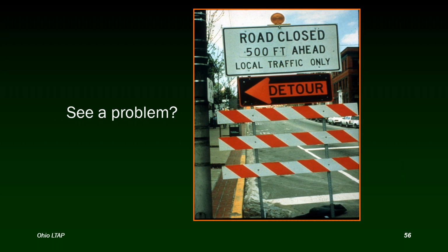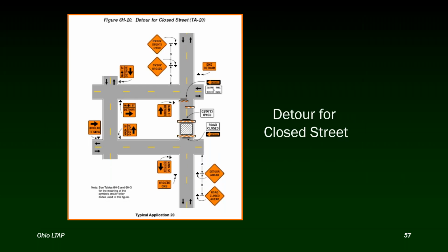They're answering now. Slashes going the wrong way. Arrow one way and barricade says the other. Yeah, so yes, that's correct. So the tripped wrong direction. Sorry, the lines on the barricade are telling motorists to go to the right, and the detour says left. So good one, class. Okay, what's this one say?